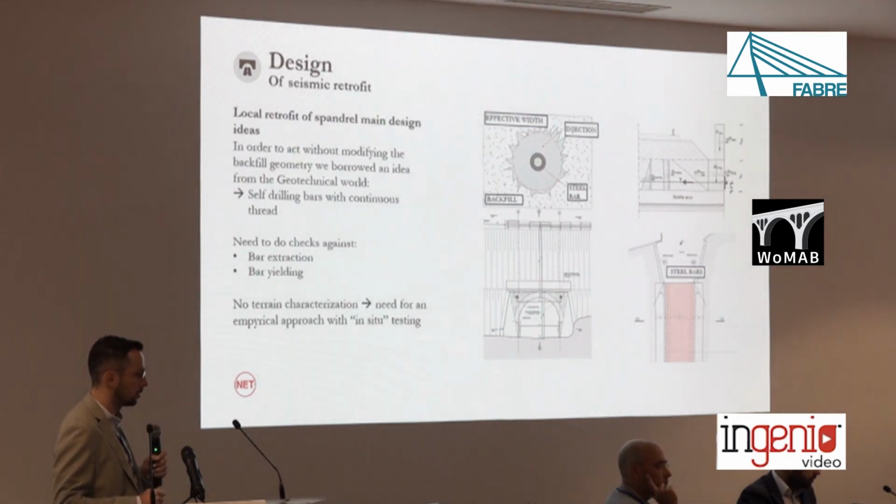So we had to maybe borrow an idea from the geotechnical world, being self-drilling bars with continuous thread that, thanks to the cementitious injection, can resist the tipping and can be easily accounted for in the kinematic assessment of the vulnerability and then the retrofit.